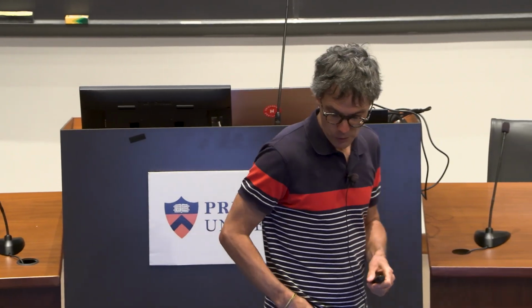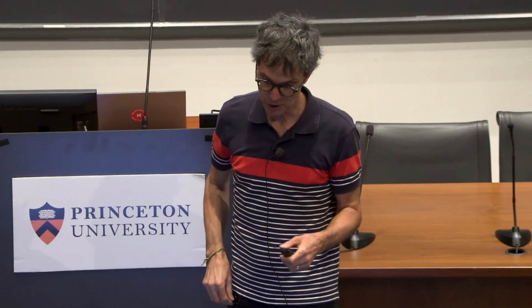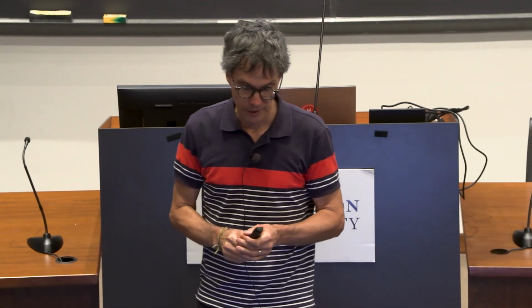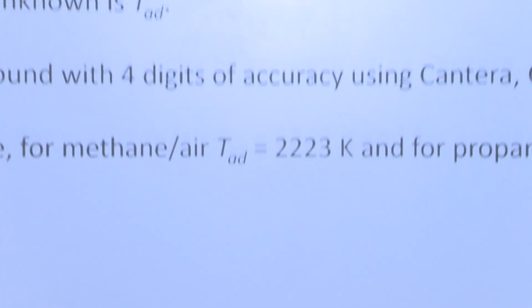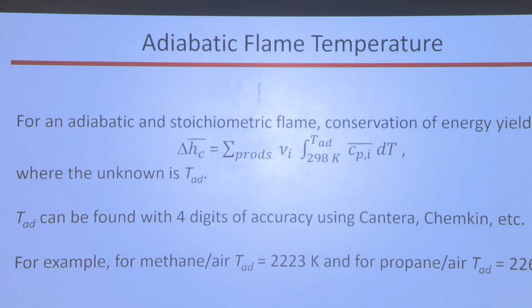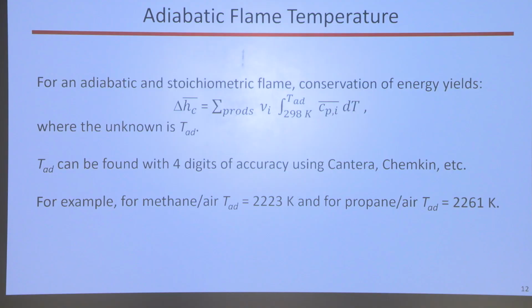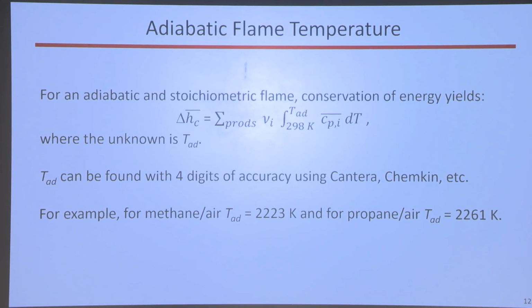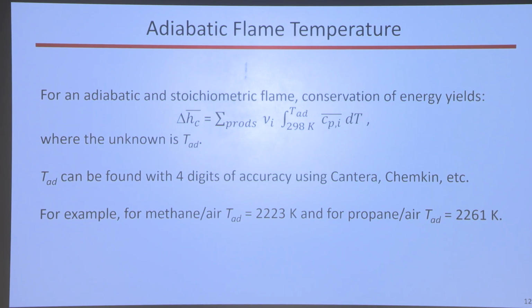Okay, so the heat release rate here is given by this equation. It's the fuel consumption rate times the heat of combustion, the lower heating value. So next, look at the adiabatic flame temperature. In the cup burner test, there's not a lot of radiation, but there may be a lot of nitrogen and carbon dioxide flowing into your chimney. And so the adiabatic flame temperature is a reasonable representation of the peak temperature in the flame. As I said, for the butane lighter, there's some radiation, probably dropping the temperature of this flame 300 or 400 kelvins. But as you go to lower temperatures, and when you remove soot, as the flame turns blue in the cup burner, you really don't have much radiative losses.